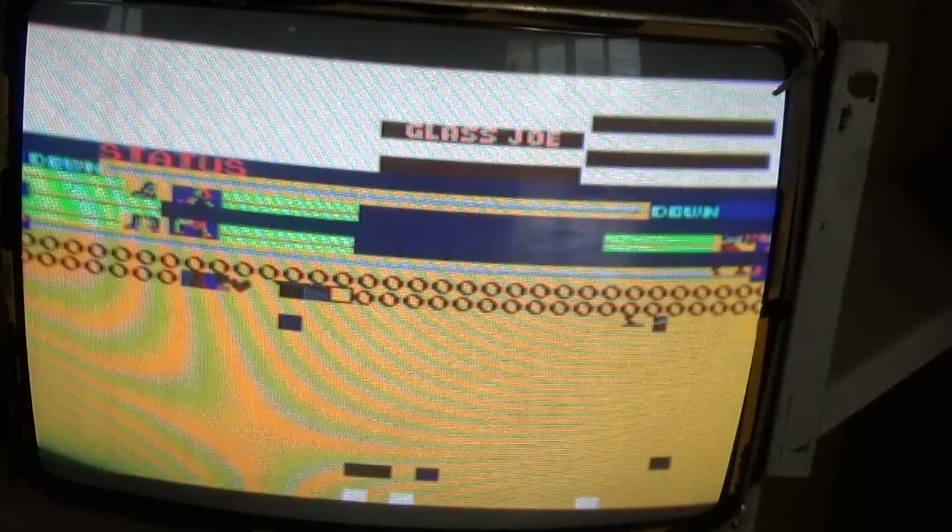It looks like my CPU board is probably good, working good. Preliminary. There's DMA stuff that is made on there. I'm going to put the Fluke on this thing and see if I can read to all the video RAMs and the video RAM on the back PCB that the CPU talks to. So I want to make sure that all of that is okay, and go from there. So let's do that. I'm going to go ahead and hook the Fluke up and see what we can talk to and what we can't.